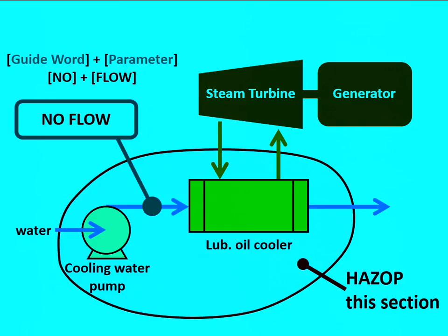Well, I think what you might do, it depends on the criticality of the situation. I know certain firefighting systems have electrical pumps. Quite common to have an electrical pump. But your standby pump might come from a different distribution board, not the same one. So if there's a problem with that distribution board, or you could have a diesel-powered pump, an emergency pump. So if for some reason the electricity supply failed to that pump, then the other pump's powered by its own little diesel generator, diesel engine.